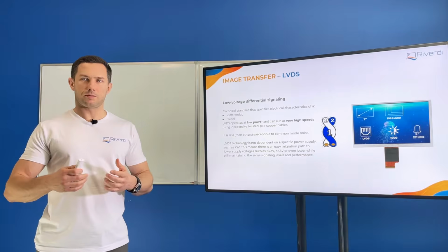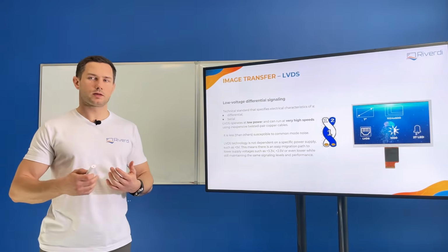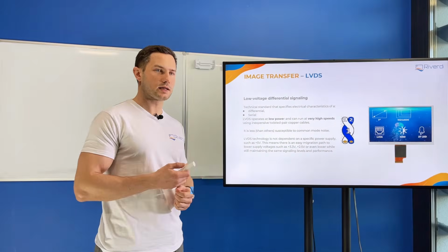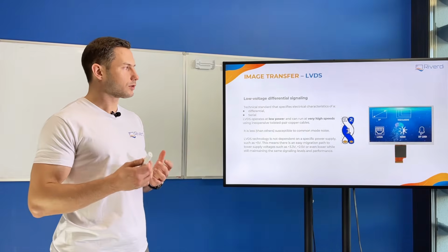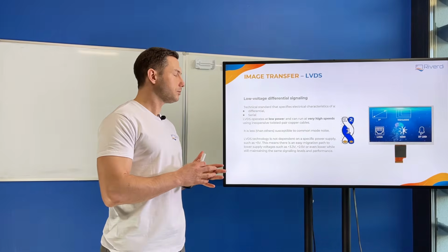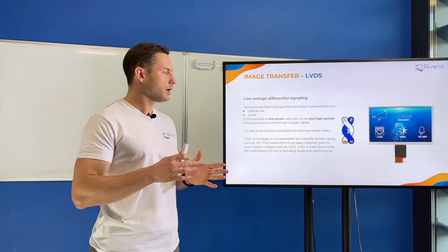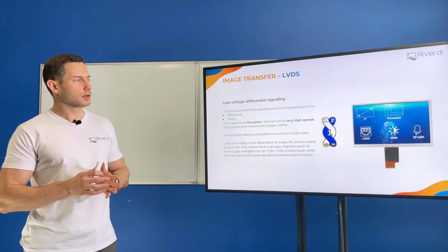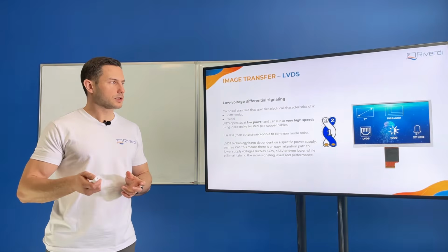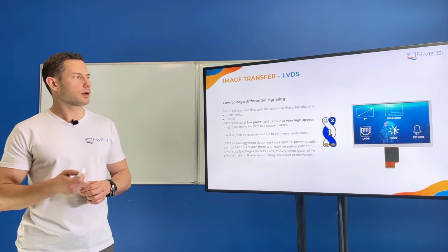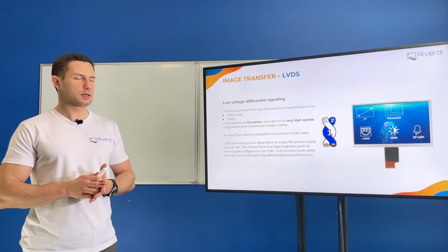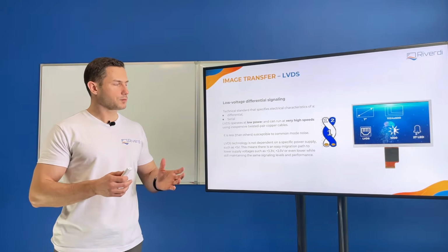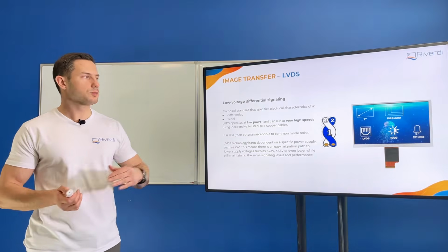and to every sub-pixel we need to deliver the data about its state, on and off, but also about its brightness, and usually it's 8-bit. So we have a lot of data. Actually, let's say it's a 2 megapixel sub-pixel display, and 8-bit. So we need like 16 million bits per frame to be transferred.